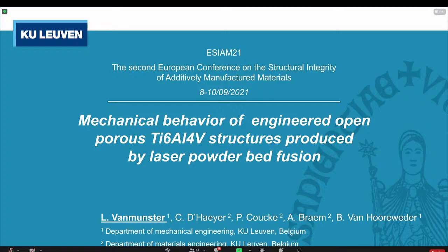I've read some of this work recently, actually, I think in Additive Manufacturing Journal, potentially. So I just have a question for you. You're basically making single tracks with wide hatch spacing. Is there a concern about trapped powders not necessarily attached to the surfaces, and removal of loose powders or powders becoming loose over time in usage? Can you comment on this?